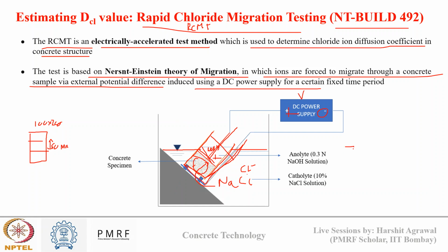Then after a certain time, say 24 hours, we'll break the concrete and check the penetration depth of chloride ions.